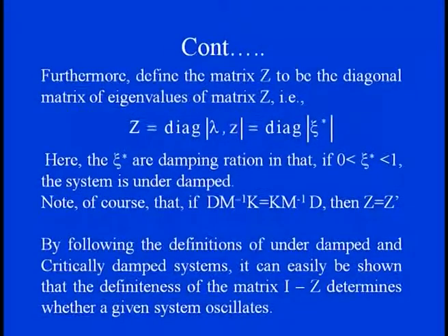Then we can easily find the eigenvalues by taking the diagonal of that. So the diagonal of lambda, z or zeta star can simply give the damping ratio, showing whether the system is underdamped, critically damped, or overdamped. By putting the values 0 and 1 together, for a higher order system the damping matrix, the mass matrix inverse and the stiffness matrix are given by stiffness, inverse mass and damping together.